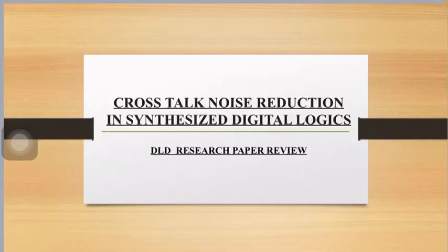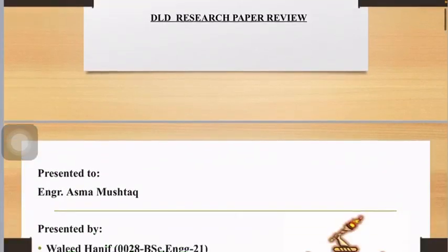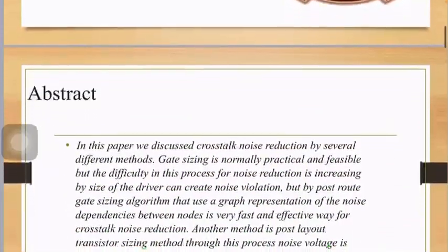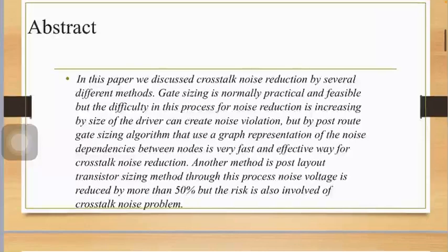As an overview, I have prepared slides of my research which will help us easily understand what crosstalk actually is and how we can reduce it in synthesized logic. Here is the abstract: in this paper we have discussed crosstalk noise reduction by several different methods. The important methods are gate sizing and transistor sizing.